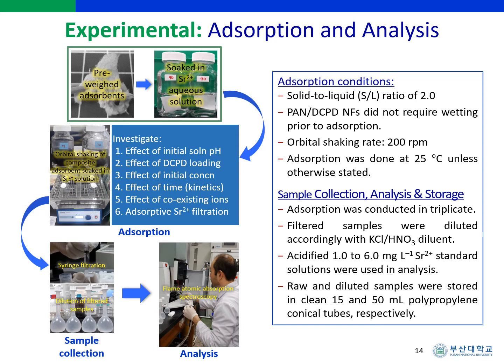To evaluate the influence of competing metal ions on the selectivity of PAN DCPD-NF for strontium uptake in terms of distribution coefficient, or KD, adsorption using strontium-spiked artificial seawater, or ASW, was performed. PAN DCPD-NF was also employed as a membrane for the dead-end adsorptive filtration of strontium ions.